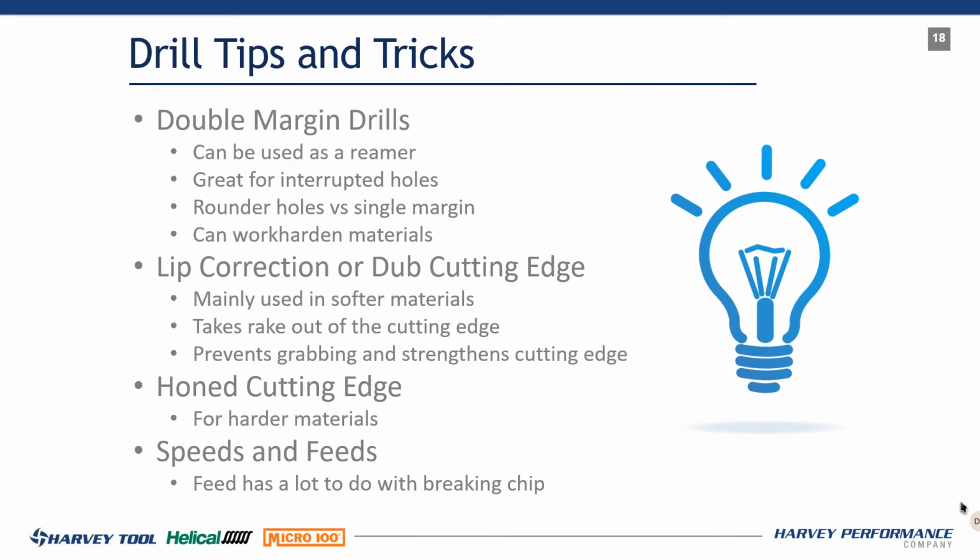And speeds and feeds. One thing I wanted to put here on tips and tricks. It's all about the chip, right? We said we got to manage the chip. If you are drilling a hole, whether it be in a mill, in a lathe, with a hand drill's a little bit out of it. But if you're drilling a hole and you just can't get the chips manageable, a lot of materials don't want to break a chip. Depending if it's 300 series stainless, it doesn't want to break a chip.